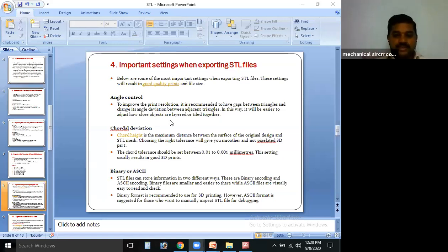But for high resolution or high performance, we have to go for some specific meshing tools, likewise HyperMesh is one of the meshing tool software. In ANSYS we have hexa mesh and tetra mesh. Most of the time we will go for tetra mesh, depending on the roughness of the component. If you want a finer component, the finest component, we have to go for more triangle meshing. Once let me show.